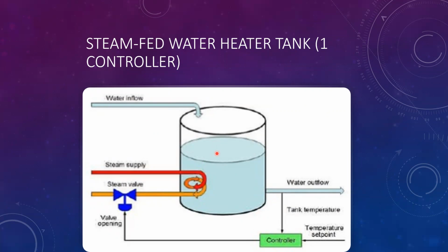But several factors could affect the XY ratio or the time required for the temperature to change, like a pressure drop in the steam supply line, or the valve could start sticking due to friction from use.